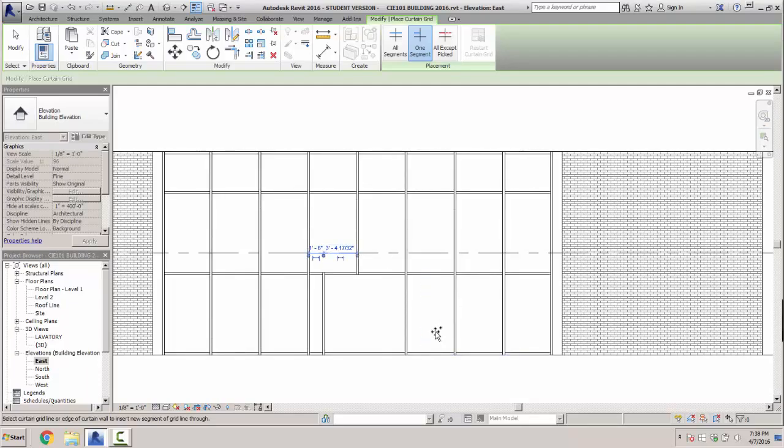Okay. Hover on the other side, the other placement. So if we hover on this horizontal, right there, just click here. And again, we'll select this and type in 1 foot 6 inches. So that gives us our 2 mullions. It should look just like it does on page 3-87 on number 12. You're going to left click on that vertical mullion. I'll hit escape